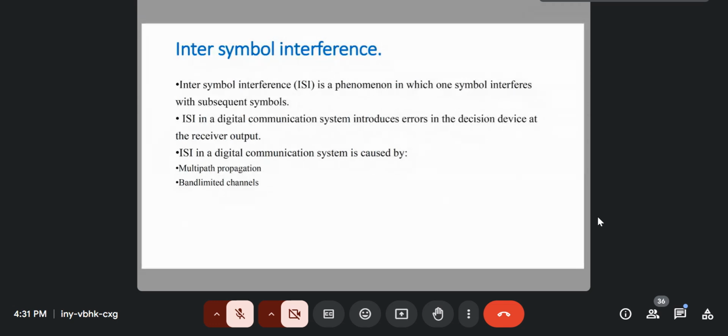When those parts of the spectrum interfere with each other, of course, it will affect the time domain signal, and it will introduce errors because the receiver will not be able to know which signal was transmitted. That's what we call errors. An error is when you're expecting a 0 and you interpret that as a 1. And it can happen because of what is introduced by intersymbol interference.